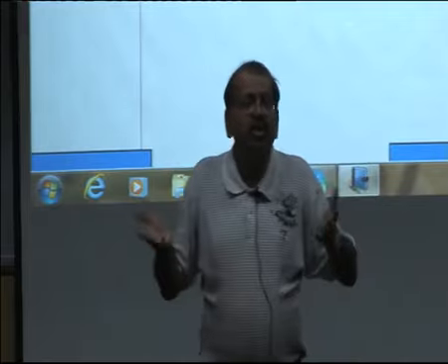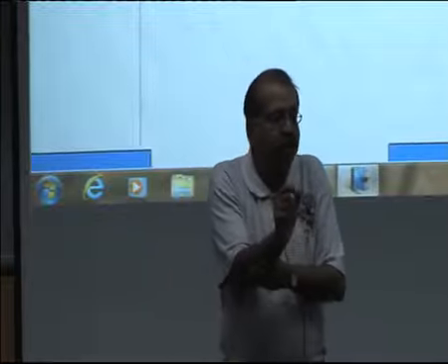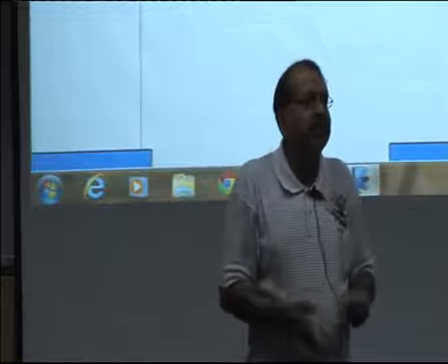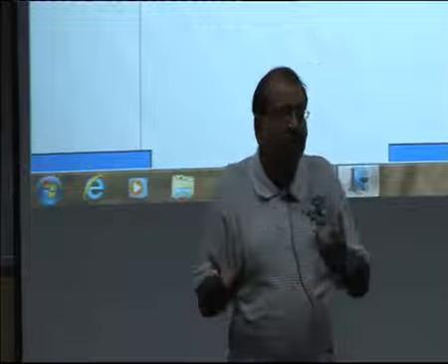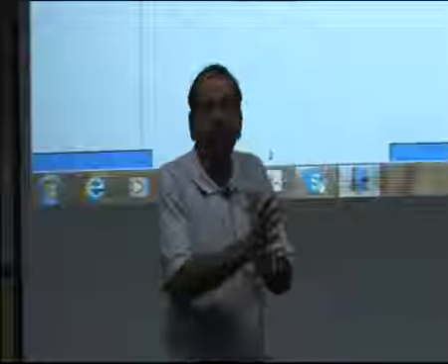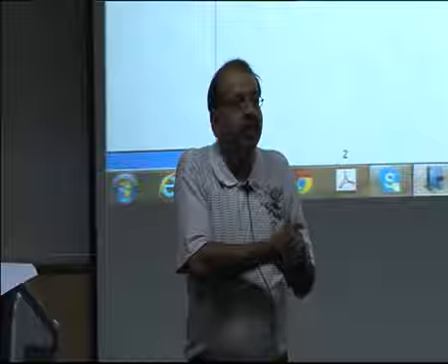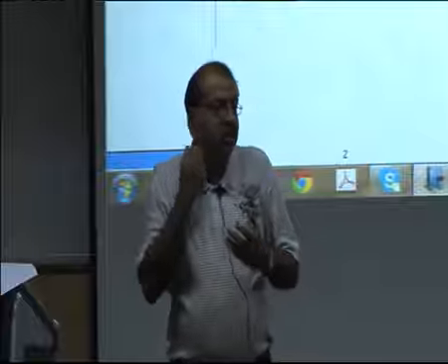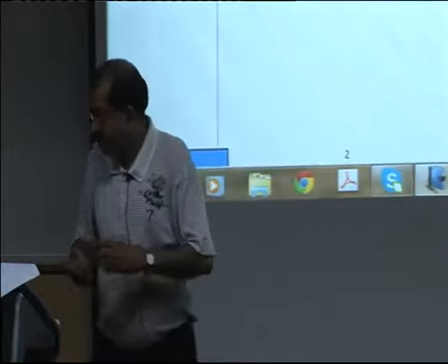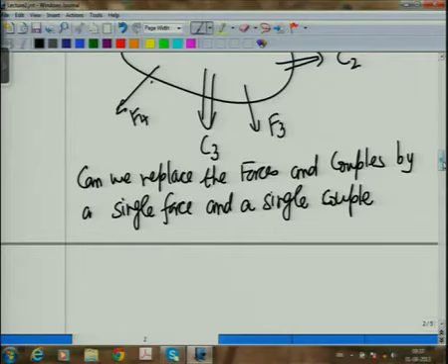We have many forces which are acting on a system. Then what we want to say is, we want to look at a particular point in the system. What is the net effect of the forces and couples at this particular point? And in particular, this may be important because the point which we are talking of could be a point of support. So therefore, if the forces are acting and if the support is able to take those forces, then it's fine. Otherwise, we'll have to modify or redesign the support. So that was the motivation of these, and we'll also say sometimes it helps us in simplifying problems.